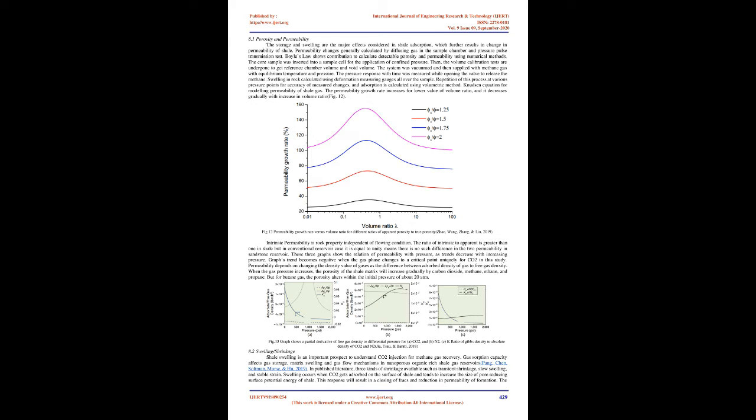This graph, Fig. 8, shows the flow of displacing fluid in two assumed sections of shale reservoir rock, stagnant and flowing regions. N2 mainly deals with the easy flowing region in free state and acts as a displacing agent by sweeping CH4 from meso and macro fractures to microfractures. CO2 deals with the restricted zone of the formation as it flows into micropores because of its linear molecular shape. This also shows that migrations of injected CO2 and N2 along the adsorption column are different.